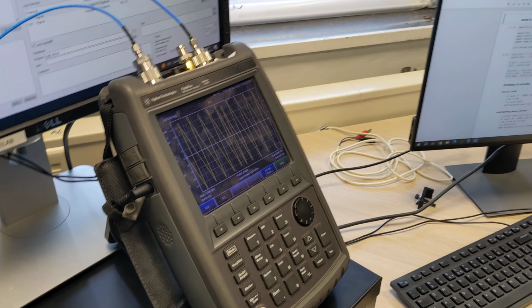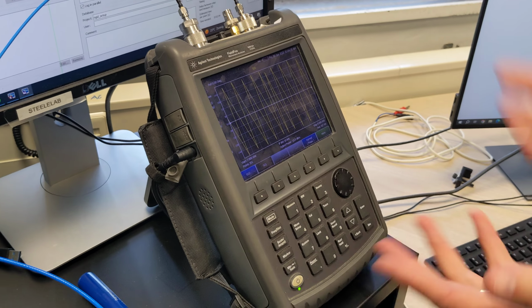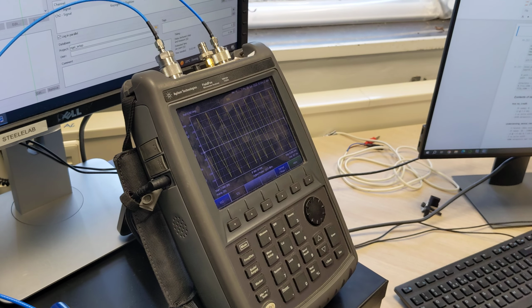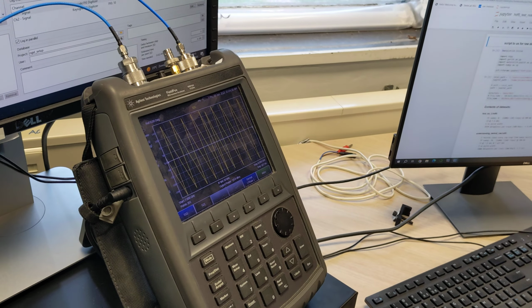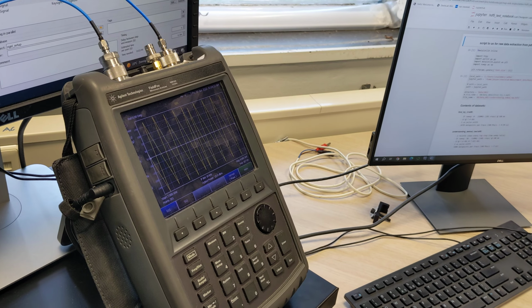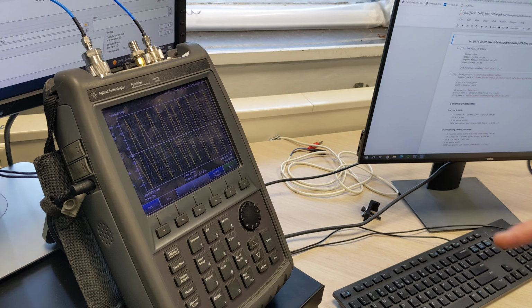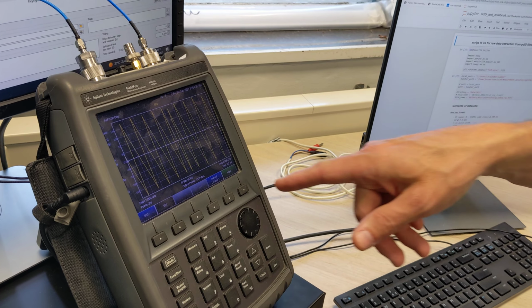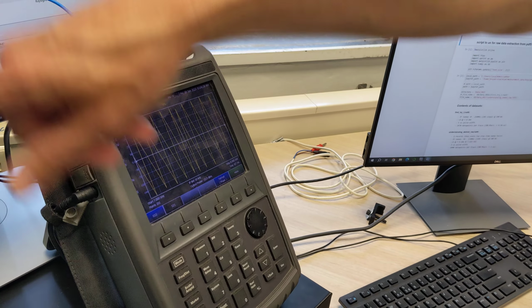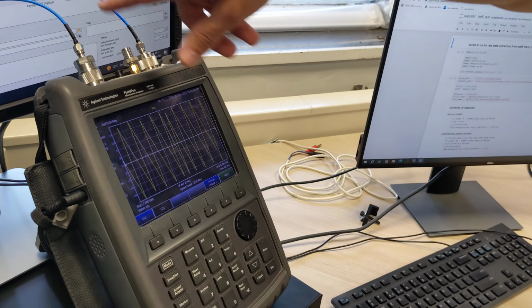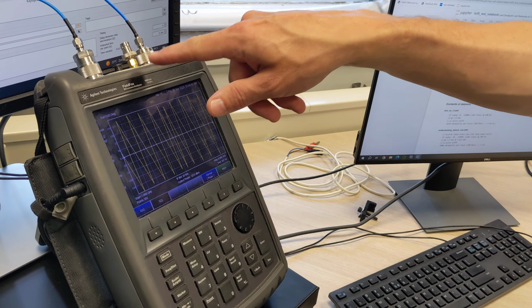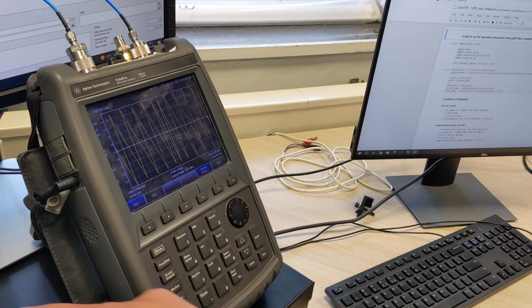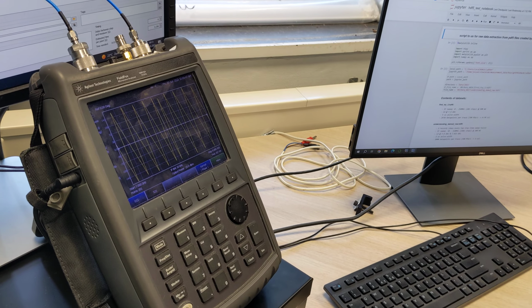If you want, we can also look at the phase. You say, oh, it should be in the phase, but what is this? It looks like some sort of crazy triangle wave, and I don't know what's going on. This is something we're going to need to correct if we want to look at the quadratures, because what you're seeing is the accumulated linear phase associated with the cables going from the device to the reference plane of the device we want to measure.